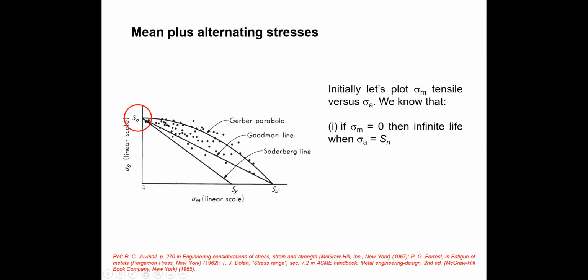So if you increase the stress with time, what happens? At the yield point, it will yield. Then it reaches the ultimate tensile strength level, and then it will fail. So this x-axis is simply a tensile test. Even for compression, it is the same manner.